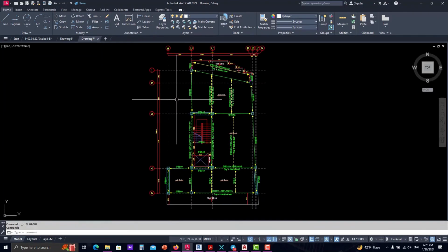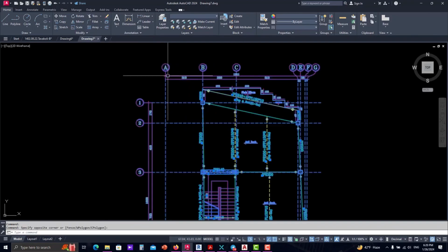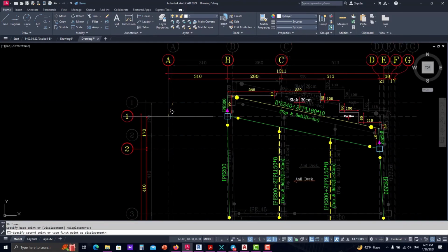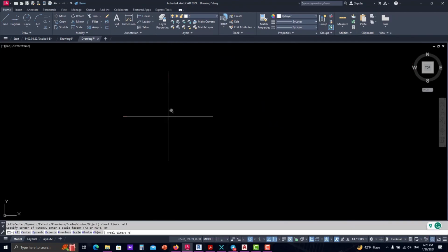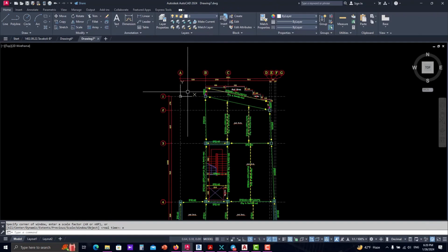Following that, I'm gonna open another plan view, which is the structural plan for the same level. We select it, then grid 1, A1, M enter, then I put the point and then I move it to the original coordinate, Z enter, E enter, zoom extents.